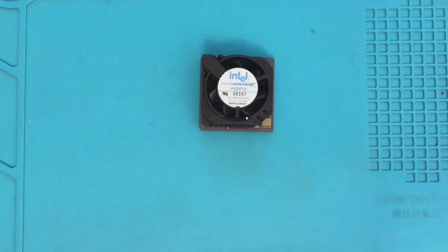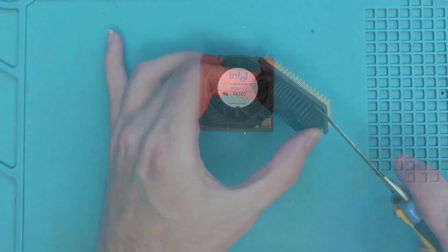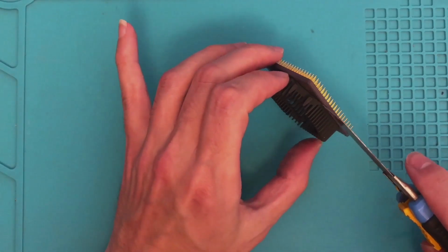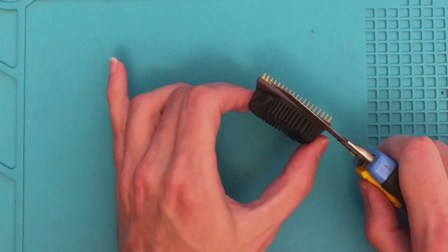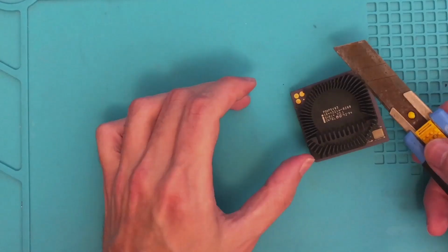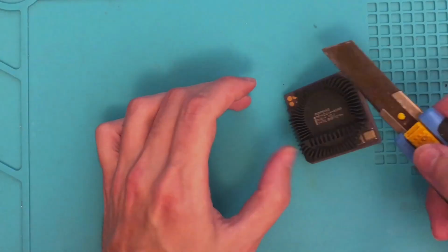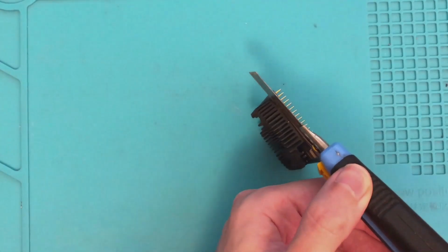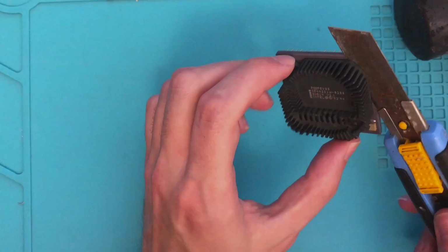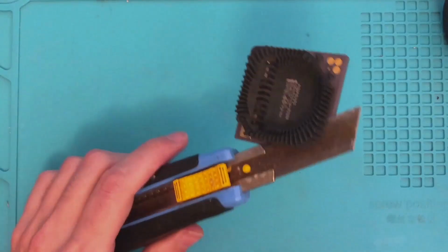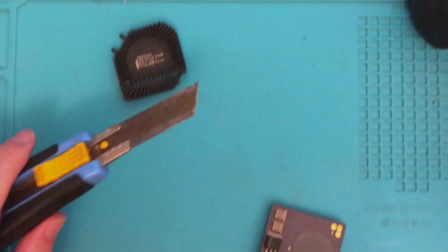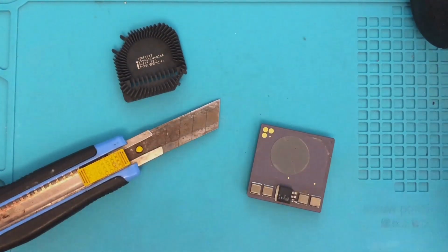My goal, of course, is to improve the cooling options here and mod the voltage regulator so that we increase the V-core. So first of all, I started by removing the stock cooler. To do this, first I remove the fan, and then I use the knife here. You just have to push it a little bit in, something like that. This is the first step, and then I just had to hit it with a plastic hammer, somewhat gently, and slowly but surely this goes in deeper, and then here I continue, and we are here. So in the end, just a little bit more. It's actually very easy to remove the metal here.